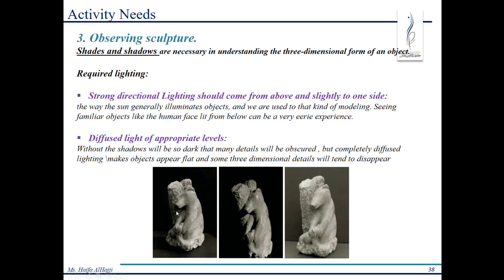The same concept applies when you are, for example, modeling a 3D shot of an exterior building, say in 3ds Max, and you are locating the sun. Usually, don't locate the sun behind the camera where you are looking at the building. Don't put it directly from the side, at a direct angle from the camera, and neither put it from the back or the top.